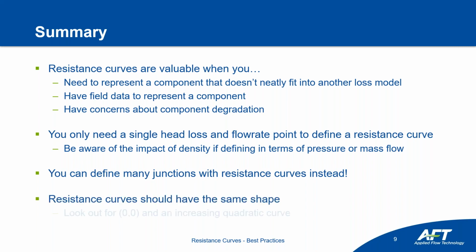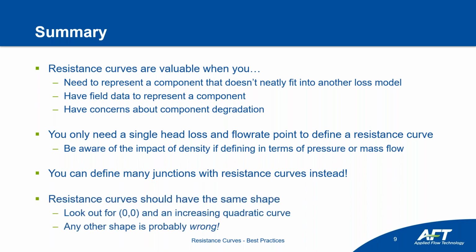And then again, if you take nothing else from this webinar, all these resistance curves should have that same shape. You want to look out for that 0, 0 point, and you want to see that increasing quadratic curve. Any other shape is probably wrong or maybe better represented with a different component, as we saw with the constant pressure drop control valve.